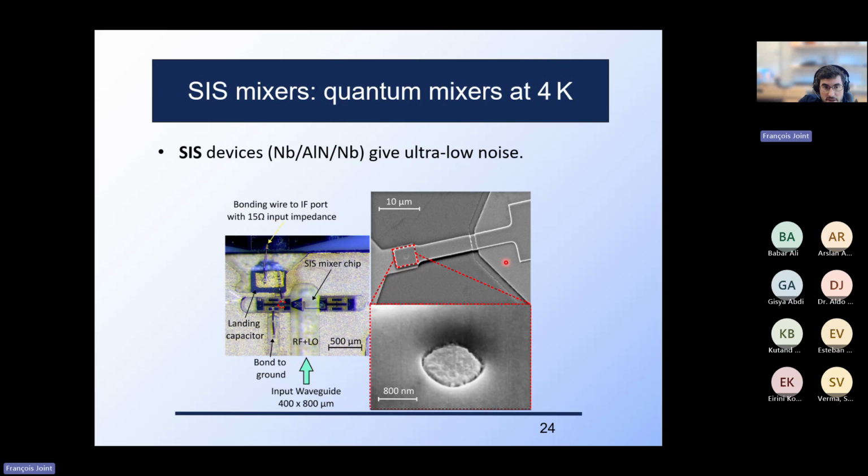Basically, this device helps to combine the sky frequency with the local oscillator, and the SIS is a high nonlinearity that allows down conversion into an IF. In band 5 and band 7 in ALMA, we use a 2SB architecture to keep USB and LSB cleanly separated.